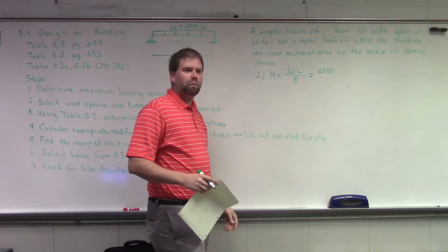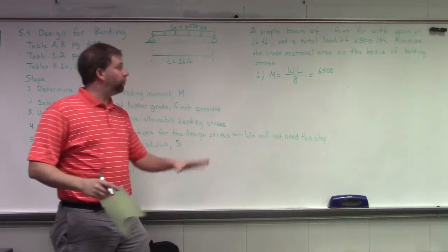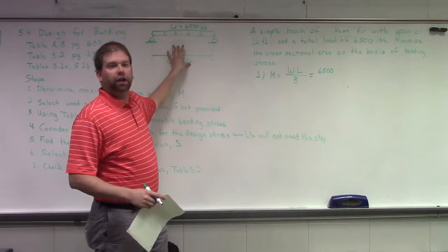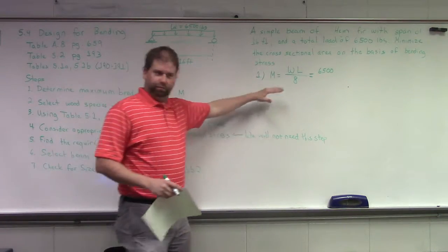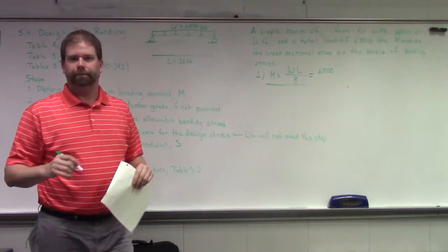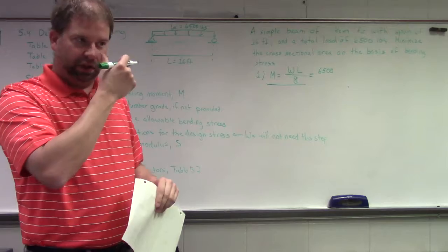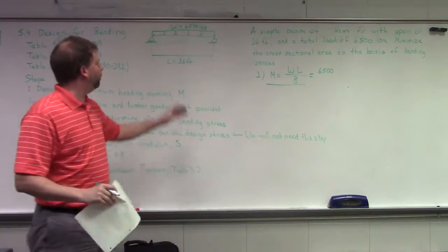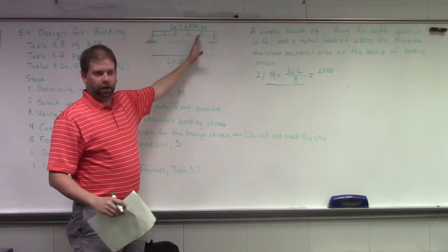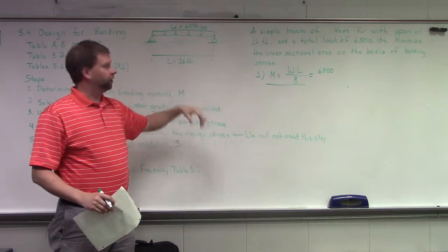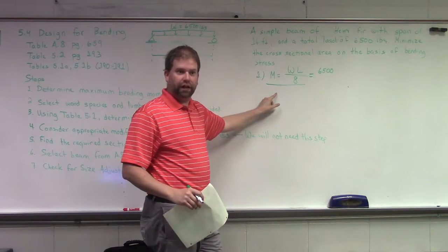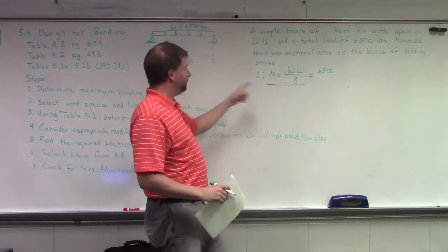So would that carry for all the problems? For all the problems that you're going to use, yes, you're going to have a uniformly distributed load. This is the only moment equation you need. I'm not going to give you one where you're going to have loads distributed here and here and L over 3, L over 3, right? Because think about when we did the flexure calculation for the concrete beam. We used a different equation.